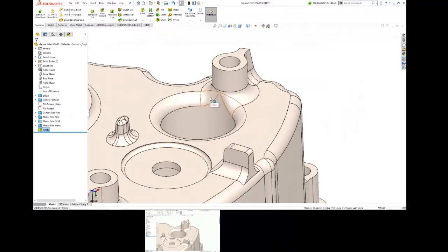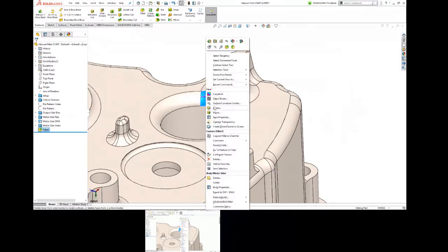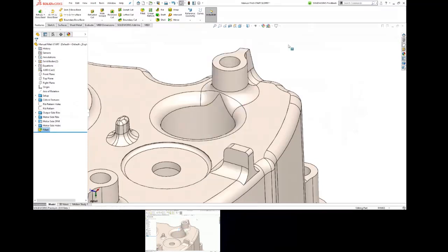So I guess the solution I would like to imagine is almost similar to if you've ever done drywall repair. You cut out the bad region and you patch over it with a good region. So we're going to try that type of approach. This is going to require us to, number one, delete the face that we don't want, possibly trim away any extra geometry that we don't want, and then use some basic surfacing tools to smooth over with it. It's about a 3-step approach. First step is the delete face command, which is typically found in the right mouse menus. There it is, delete. I use this all the time, so I customize that on my S key.